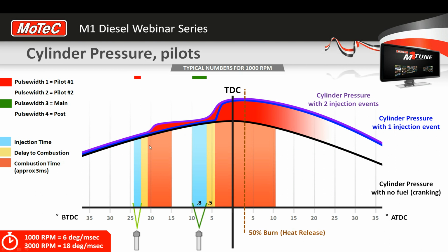So the idea of the pilot is just to do a little preheating amount in the combustion chamber, and its purpose mainly is to soften this pressure curve, this pressure rise, and take it from a really sharp pressure rise and kind of lead a softer increase in fuel or that combustion burn. It has the net effect of just quietening down the noise from the engine, and for racing, realistically, you don't need it. We haven't been able to prove that it does make more or less power.